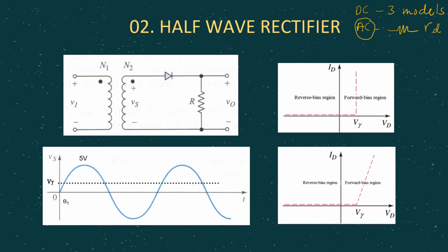But you should take note that for this AC analysis, normally the AC signal is in the form of low voltage in the range of millivolt. Then only we can do this representation of diode modeling, where the diode can be replaced with a resistor RD, when we deal with a small AC signal in the range of millivolt.